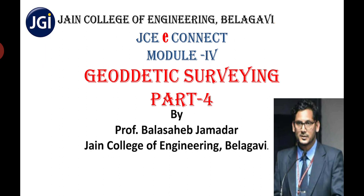Objects such as church spires, steeples, flag poles, and towers are sometimes selected as triangulation stations. When observations are to be taken from such stations, it is impossible to set up the instrument over them. In such cases, a subsidiary station, known as a satellite station, eccentric station, or false station, is selected as near to the main station as possible, and observations are taken to the other triangulation stations with the same precision as would have been used in measuring the angles at the true station. These angles are later corrected and reduced to what they would have been if the true station was occupied.